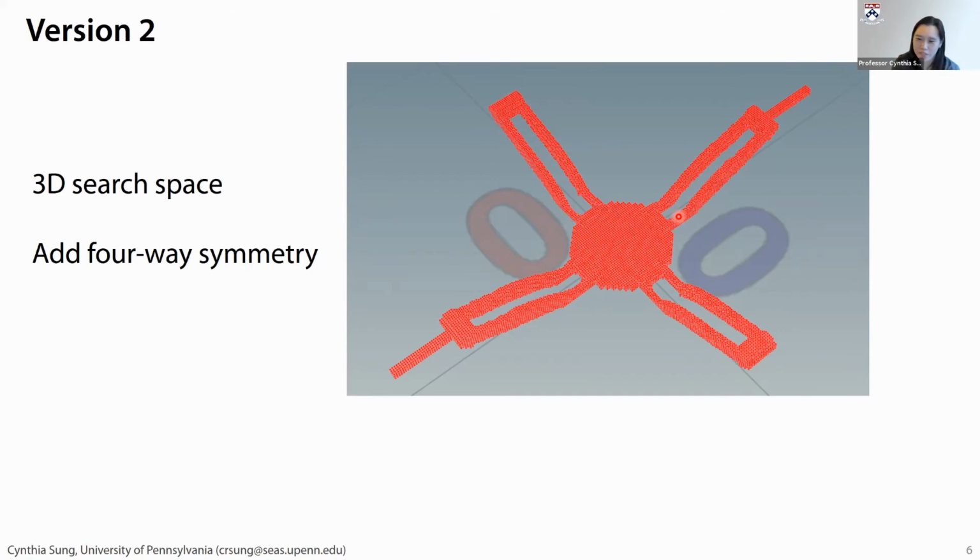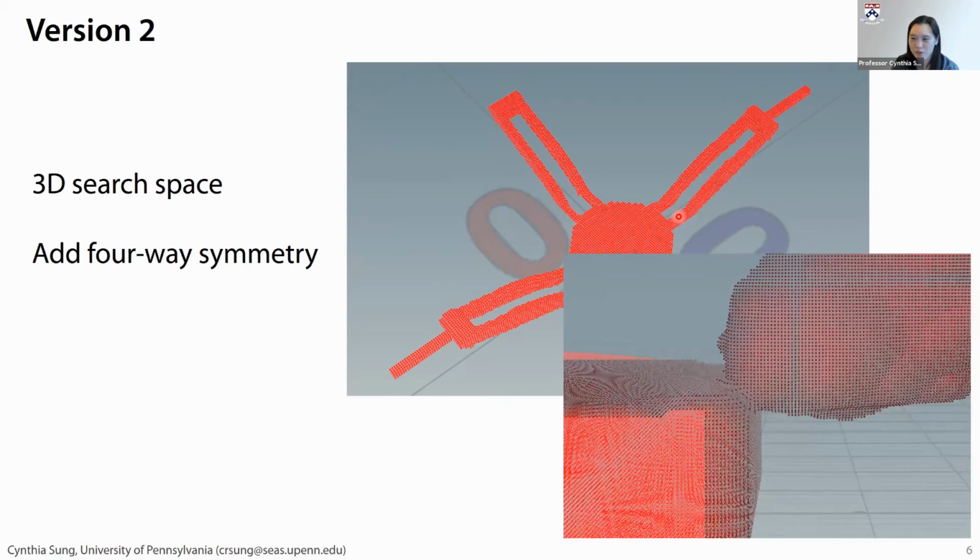Now, the problem with this then was that, again, we were just using a standard objective, and there was nothing about fabrication constraints. So if you zoom in to this optimized result, you get some areas that look like this. They're very small hinges, a lot of stress concentration, and it works well in simulation, but if you fabricated this thing, it would probably rip apart, or it may not even be able to be fabricated at all, because we were using a 3D printer with not very good resolution.